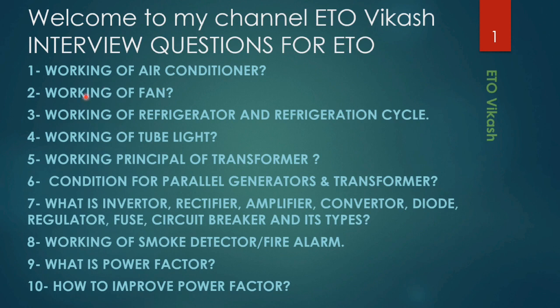And now the second question is working of the fan, a ceiling fan. What motor are we using? We are using a single phase induction motor, which is not self starting. So for self starting, we are using a capacitor. And the third is working of refrigerator and refrigerant cycle. The refrigerant cycle I have already explained: compressor, condenser, expansion, and evaporator. You can also study from Google.